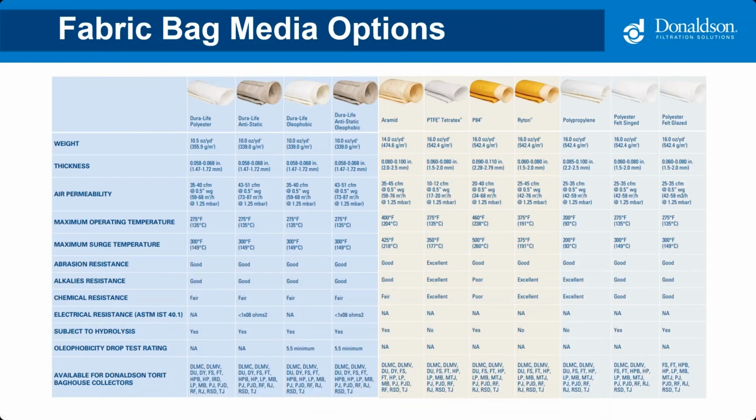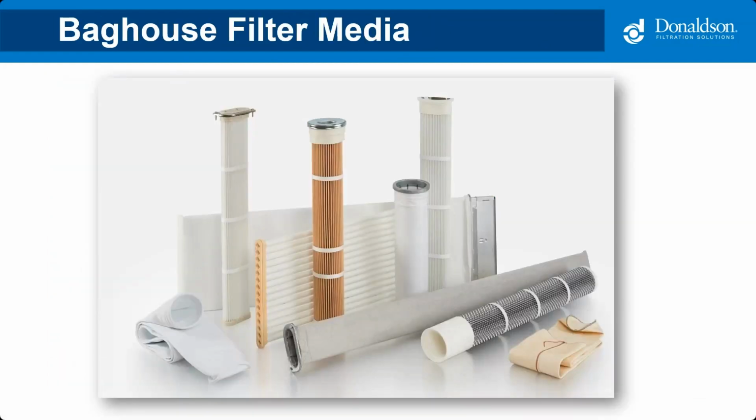Pleated bags are a one-piece design. They tend to be shorter in length and take significantly less time to change out. But not all baghouses can use pleated bags. But they are a great option in certain applications, especially if the dust is abrasive.